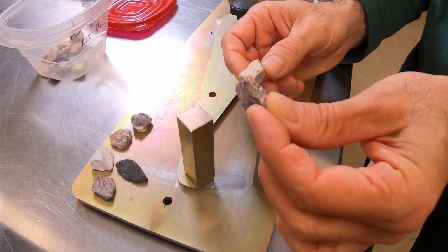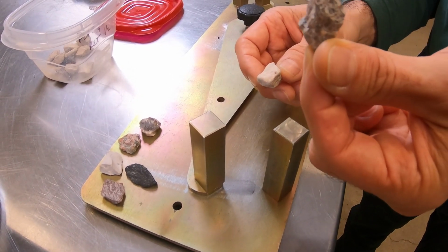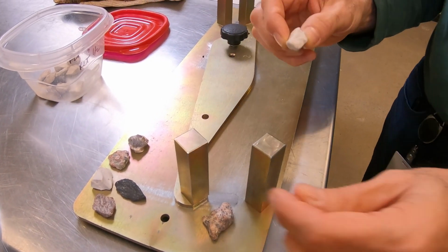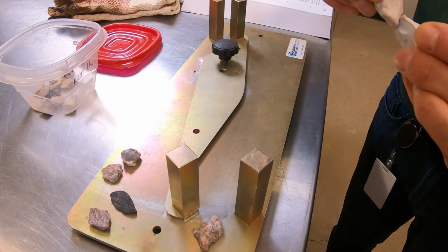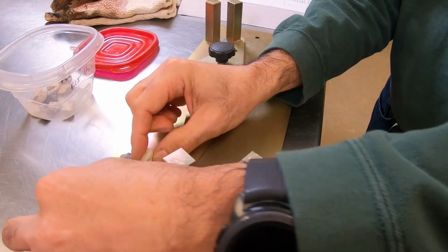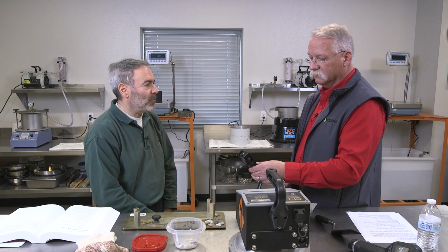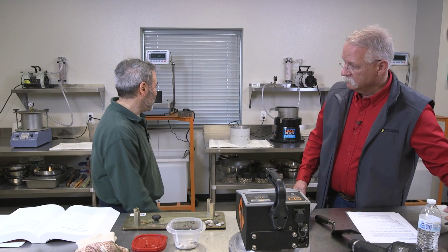And when you're looking for stone-on-stone contact, such as SMA, well, that'll break right in half. Now we've got 2 rocks instead of 1. Versus the nice cubical rock that locks together, it's not going to crush or fracture. Gotcha. Okay, awesome. Very fundamental.